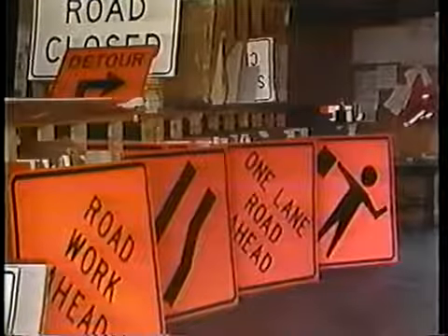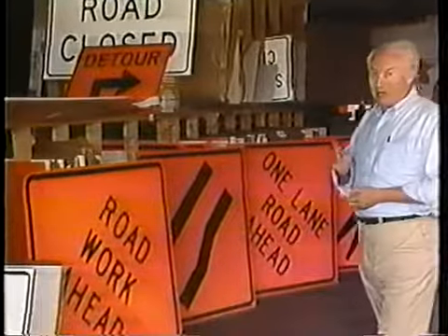Traffic control devices include signs, signals, lighting units, pavement marking, delineators, channelizing devices, and hand signals or flags, which are used to warn, guide, or regulate traffic. This part discusses elements of design, proper application, and placement for these devices. Signs are classified as regulatory, warning, and guide signs.